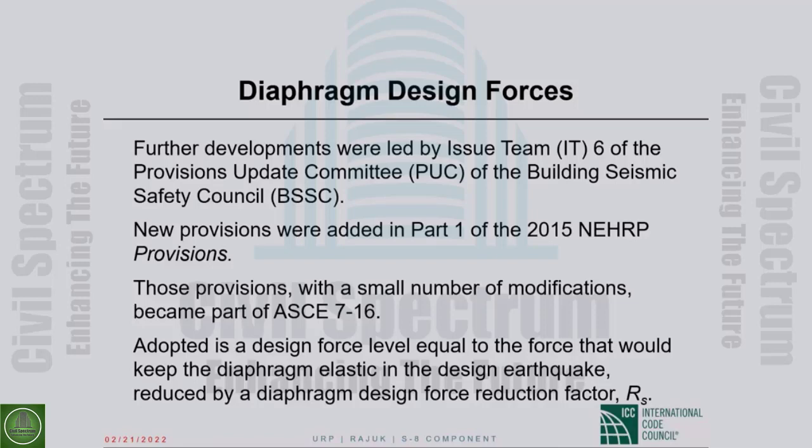Yeah, the second and the third part of your question is not clear, but a slab on grade can be, and it is required to be designed as a diaphragm if you transfer lateral forces through it. The lateral forces may be from columns, maybe from shear walls. If it is lateral force from shear wall, then you will need some kind of collector elements or something to spread the load around. From columns, I don't think so.